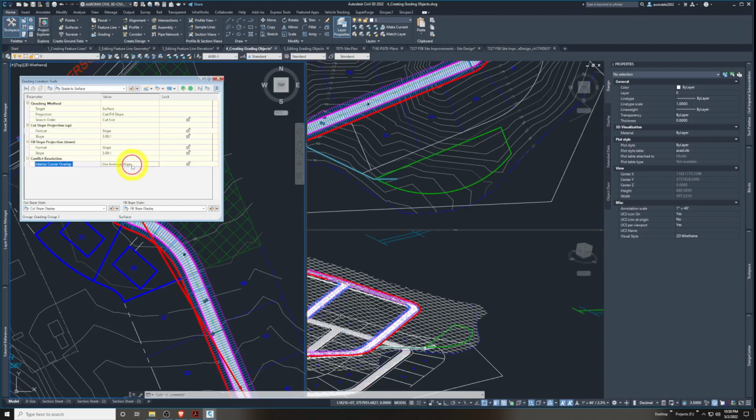And generally, this one I'll leave as use average slope, but since we have one picked, it's doing this for us. But in this case, we're going to pick grade to relative elevation, and different options will come up. You can't cut and fill because you have to pick one direction relative, up or down. Now when you pick graded distance, it says a similar thing, but you have to go a distance.